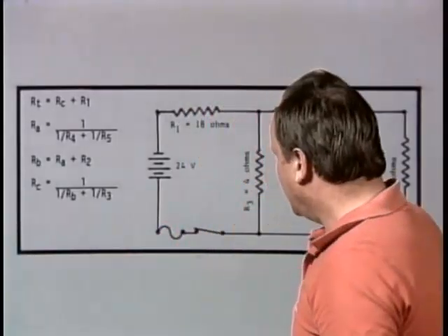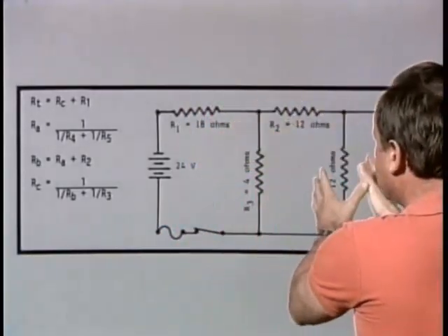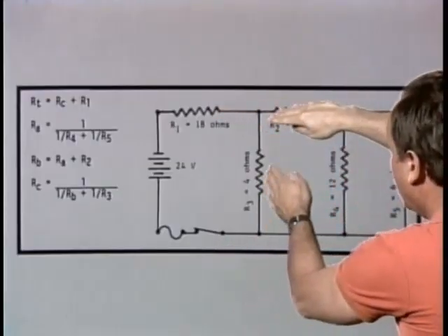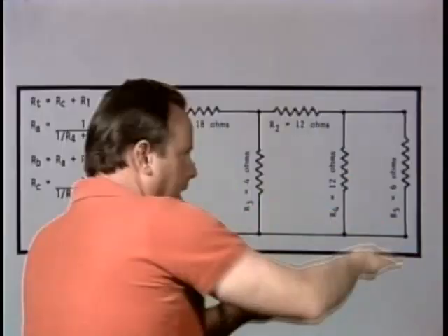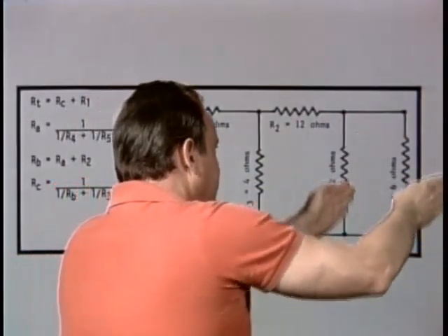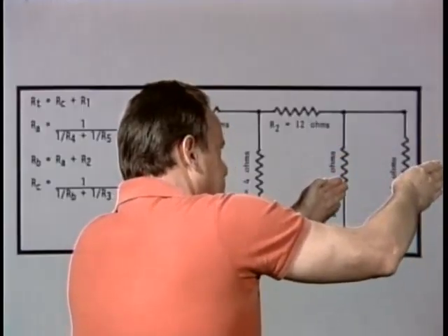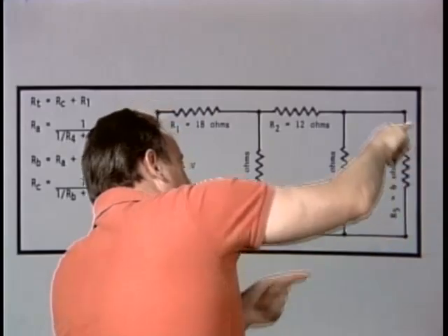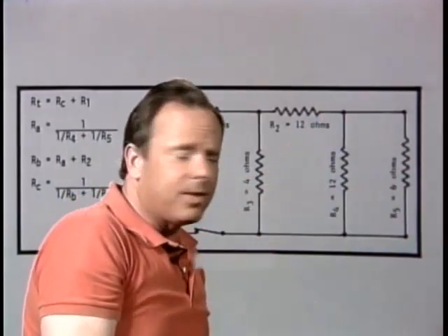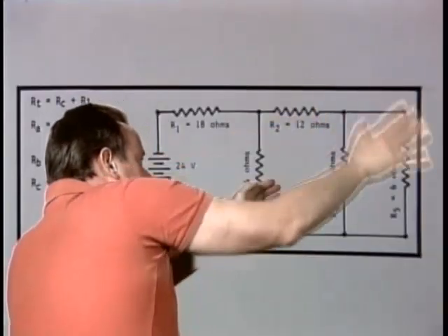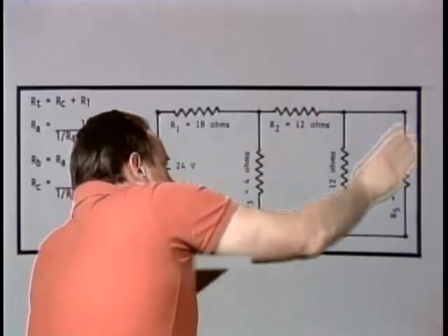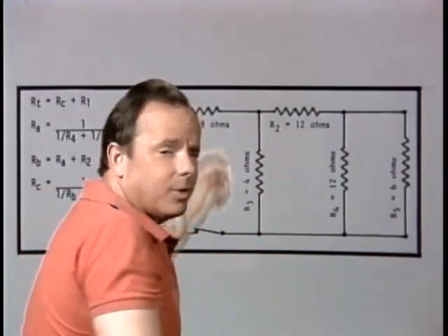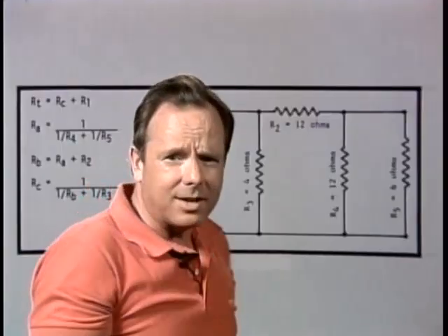Let's one more time look at that drawing to see what we did on figure 12. And what we did is we tried to resolve these parallel paths into a total resistance. We said this is a series resistance. There's only one path here, but now we have two paths. And if we go over here, we have a path with these two together. So we resolved these two right here into a total resistance. Then when we got done with that, we said, all right, now this is a series. So we added the total resistance here to this resistance here, which is in series, added them together, and we made them series. But now you have to take this whole mess and take these two paths and make a total resistance out of them. And we did that, and now all we had then was two series resistances to add together. See, there's nothing to that stuff.